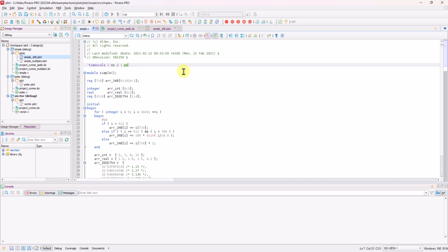The plot tool provides different plot styles that can be used to display a graphical representation of functions or relations among variables, present values of objects as a function of time or even other variables, and all the like. Plots can be a powerful debugging tool as it appeals more to how humans are able to process and see data. This could be useful for cases such as analyzing memories for image processing, looking at beam intensity data for ultrasound beamforming in medical imaging, and visualizing trajectory in digital positioning systems.